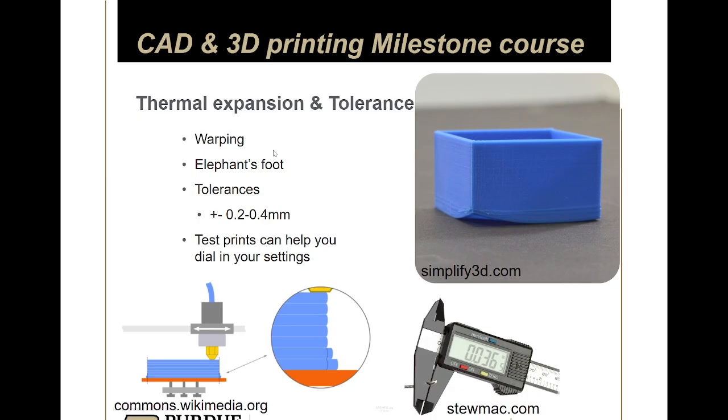The other thing, this is a little bit more technical when it comes to 3D printing, but some people might experience something called elephant's foot. It's basically when the printer isn't super dialed in, or some people do it on purpose because they want to squish the first couple layers for better layer adhesion onto the build plate.